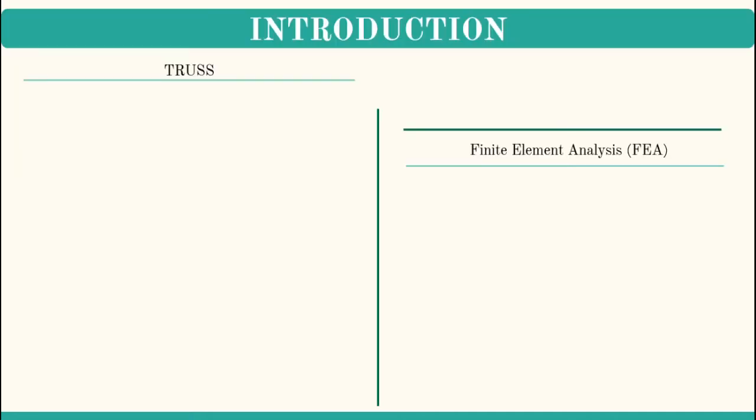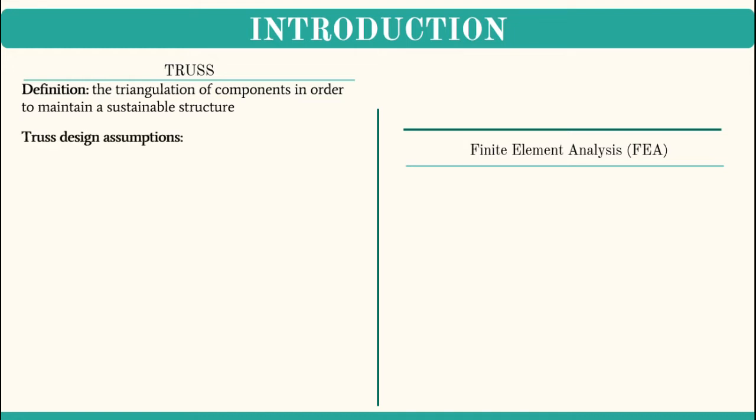First of all, I will briefly introduce what is truss and also finite element analysis. Firstly, truss. The definition of truss is the triangulation of components in order to maintain a sustainable structure. We have some truss design assumptions, which consist of: first, only the axial forces will be carried by the truss members.